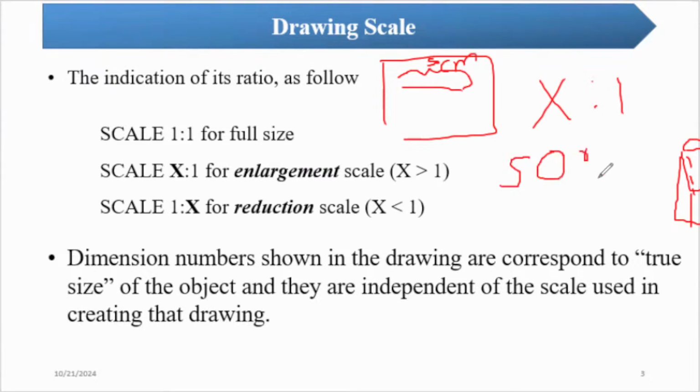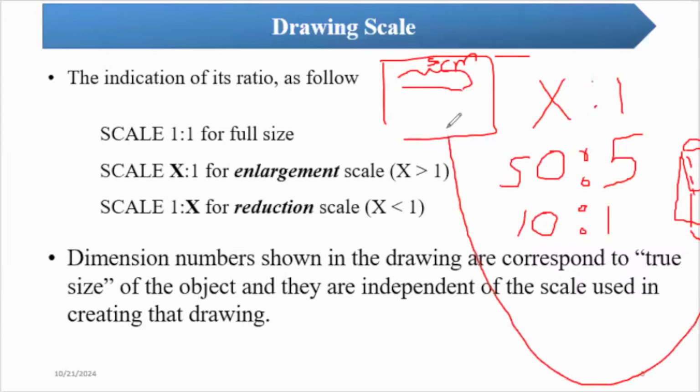So you have to convert that to one common unit. So 5 centimeter is 50 millimeters, right? If the drawing uses 5 centimeter to show 5 millimeter, we convert to millimeters to write the scale. So 5 centimeter is 50 millimeters, and the object shows 5 millimeters. We can reduce this. So every length in this object is shown 10 times bigger in the drawing. This applies to every length.